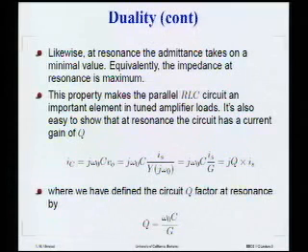And at resonance, the admittance of the circuit is just G, or the conductance. Remember, the imaginary part is 0. And so now I can define quality factor as omega naught C over G. And so I've shown that the current in the capacitor is equal to jQ times IS. Okay? Questions or comments?